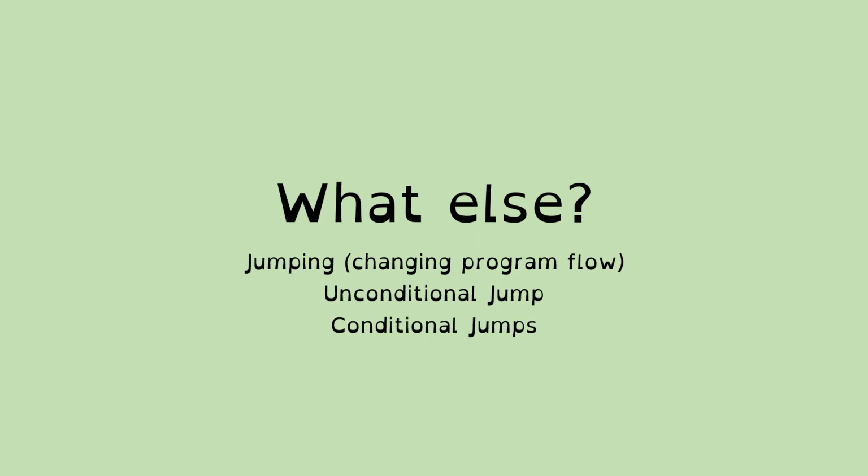And the 2 things that we're going to use for our conditions are actually the flags from the ALU, which are the Z flag, which will go high if our output is 0, or if our number is 0. And we're going to also have a jump which is dependent on the carry out. It could be useful. We just about have the space to do that.